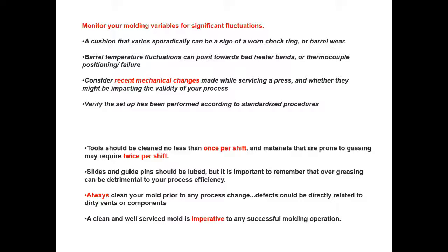Your molds definitely need to be serviced. Slides and guide pins should be lubed, but it's also important to remember that over-greasing can be detrimental to your process efficiency. For instance, if you've over-greased and the grease ends up getting into a vent, then your gas might not be escaping properly because the tool was poorly serviced.